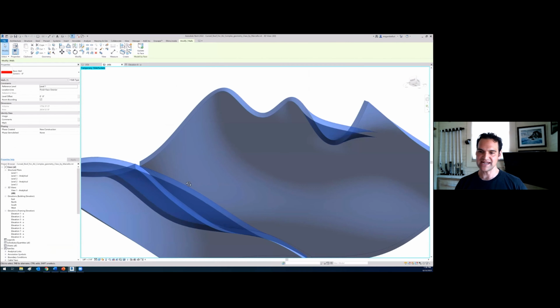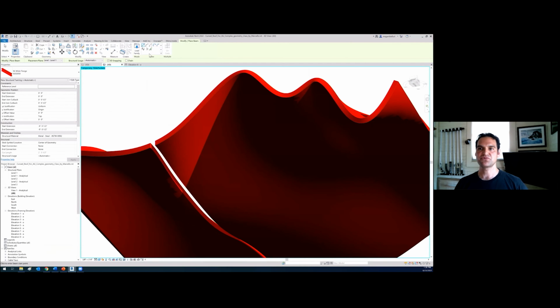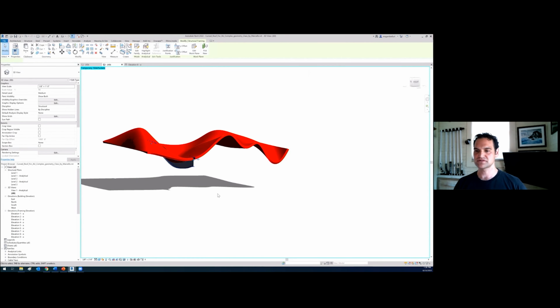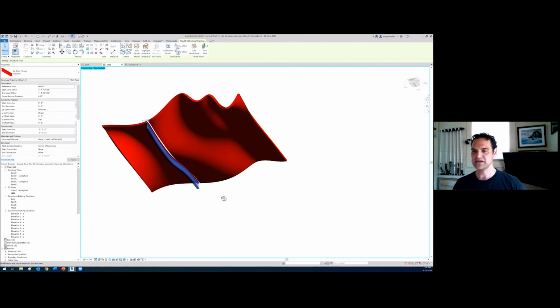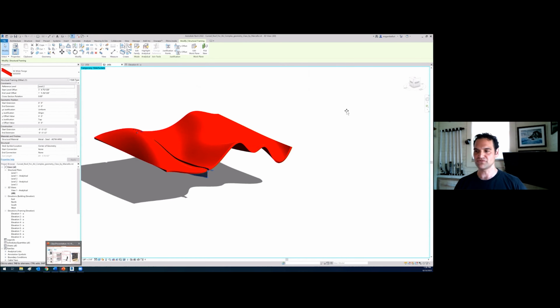And once you have an edge, then you can come to your beam tool, make sure you 3D snap, and then you can actually snap right to the edge. Look at that. And now you have a beam that actually follows a curve just by using what I call the intersection method. Okay, cool. So we went over that in intricate detail.